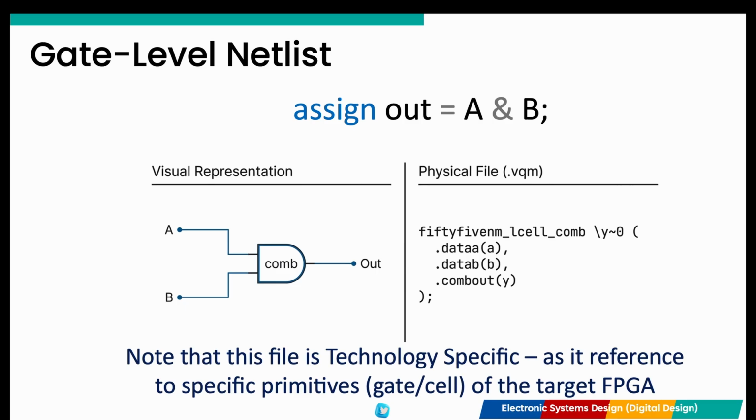The direct output of technology mapping is the gate-level netlist, typically generated as a lower-level Verilog .v file. It is crucial to understand that this file is no longer high-level behavioral code. It is literally a physical hardware blueprint. It describes the exact hardware structure at the gate level, showing exactly which lookup tables, multiplexers, and registers have been utilized and how they interconnect to form your specific design.